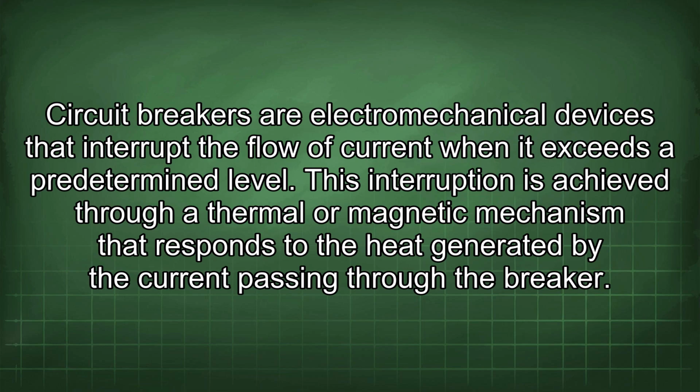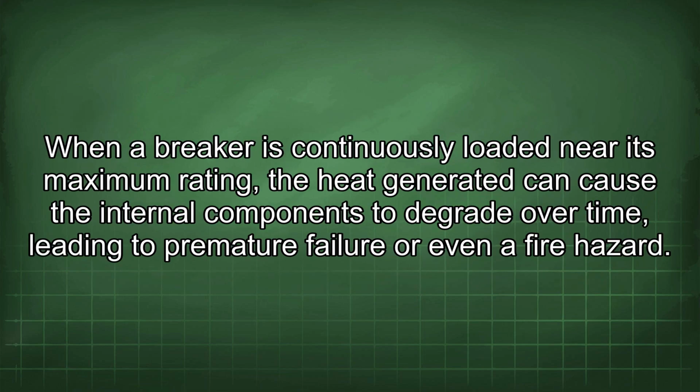Circuit breakers are electromechanical devices that interrupt the flow of current when it exceeds a predetermined level. This interruption is achieved through a thermal or magnetic mechanism that responds to the heat generated by the current passing through the breaker. When a breaker is continuously loaded near its maximum rating, the heat generated can cause the internal components to degrade over time, leading to premature failure or even a fire hazard.